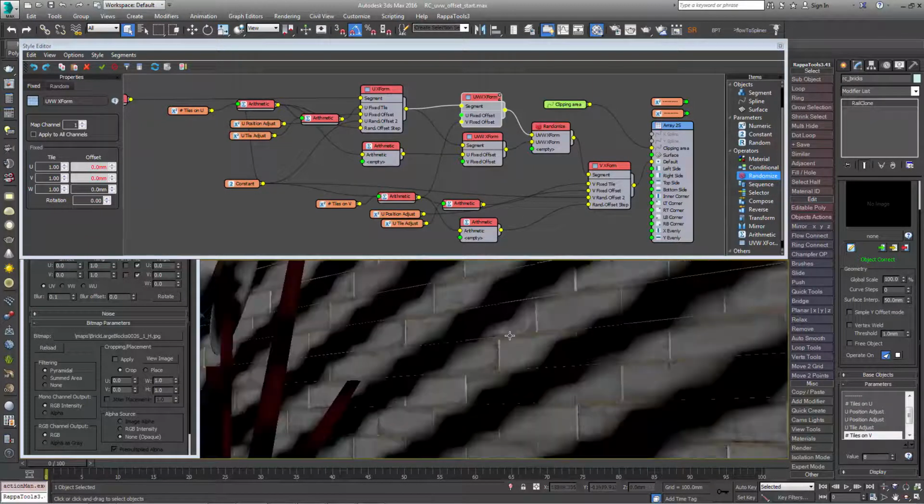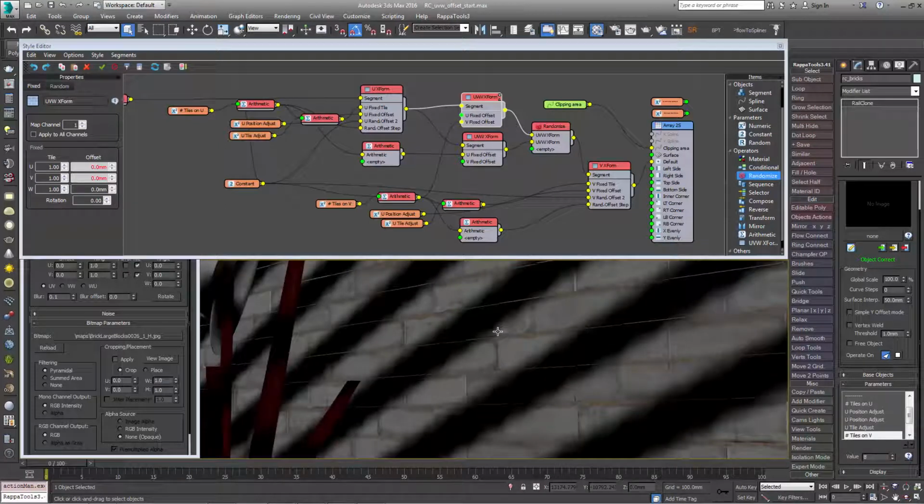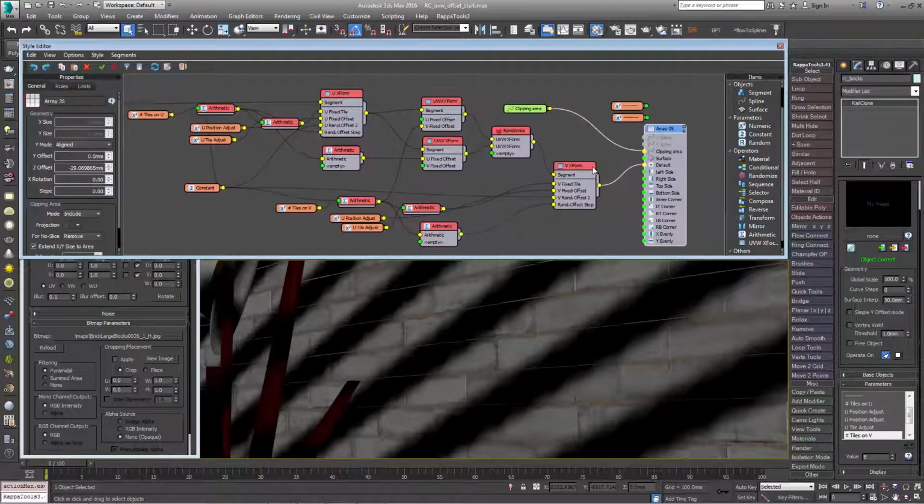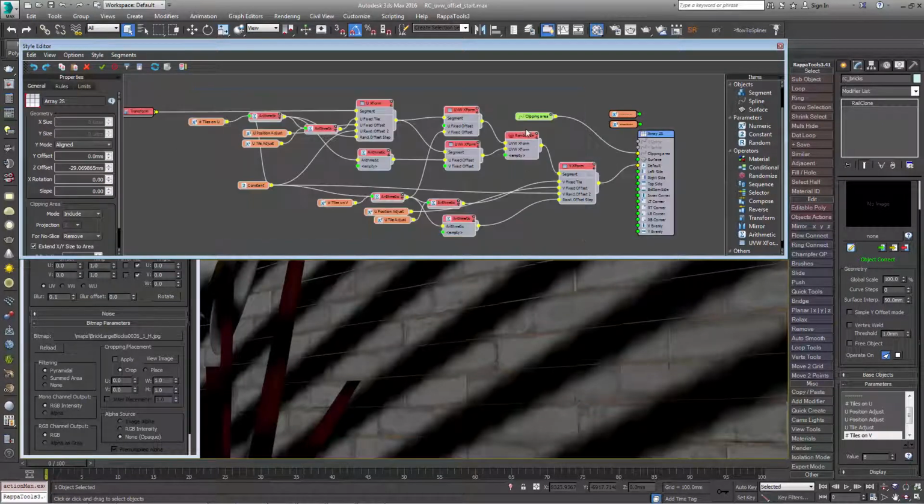This node tree looks confusing at first, but it's a good demonstration of how you can use arithmetic operators to create complex relationships between nodes in Railclone. The good thing about this setup is that you only have to do it once. Now that you've got this node graph, you can copy and paste it into any style where you might want to sample parts from a tiling texture.